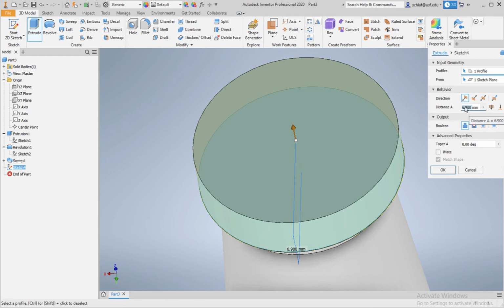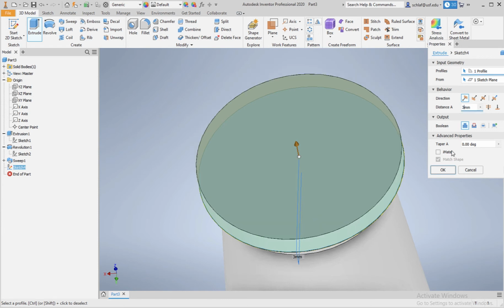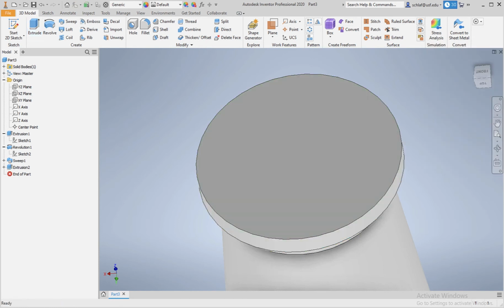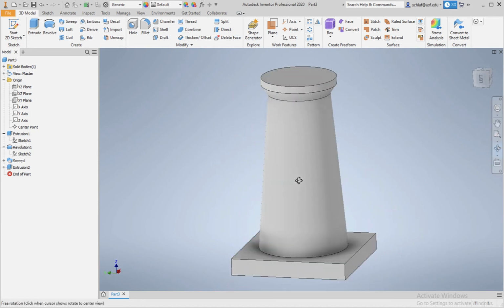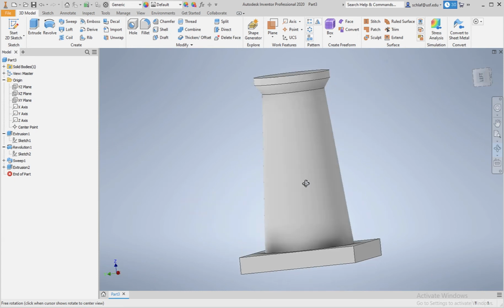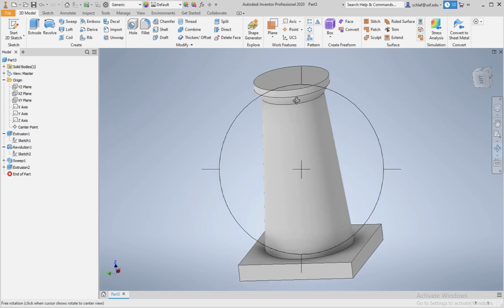So in my experience, 10 layers or so is good to recover and create a nice flat layer. So let's put 3 millimeters in here, so this will give us 10 printer layers. So you see now we have here a growing lighthouse. So the next step is to put a structure on here to house the actual light.